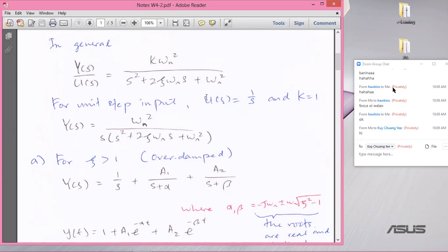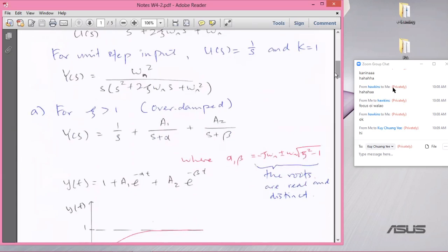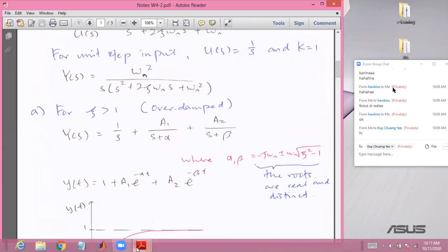That is why we categorize the control system according to order, regardless of whether it is a translational system, rotational system, or whatever system. As long as you obtain the gain k, zeta, and omega n, you already have the system response.